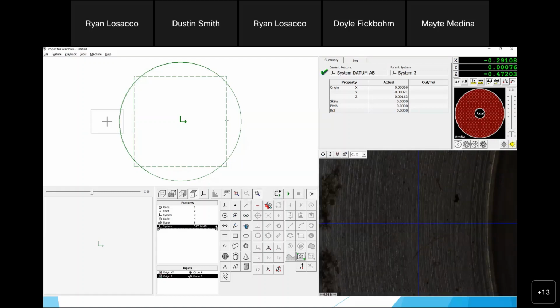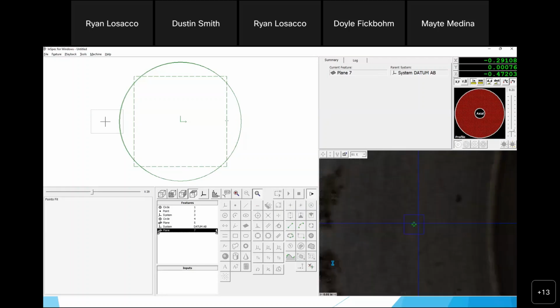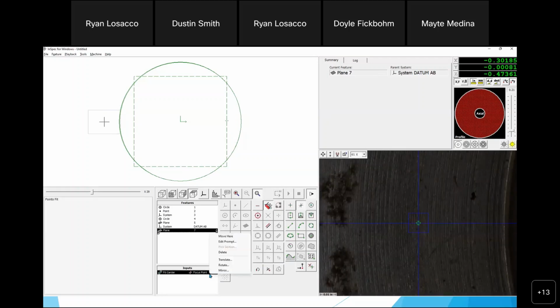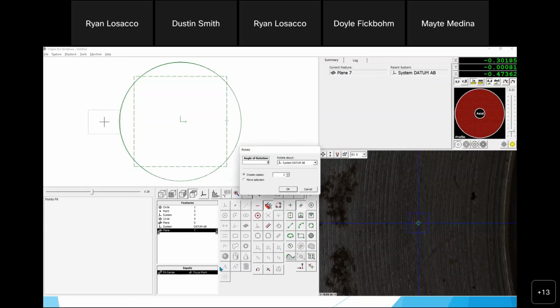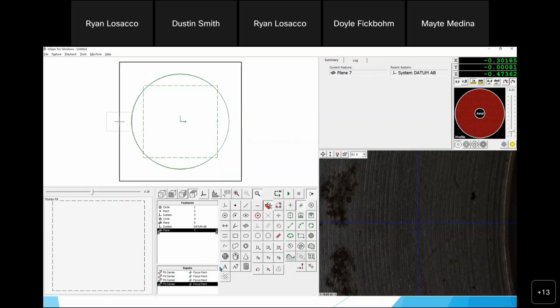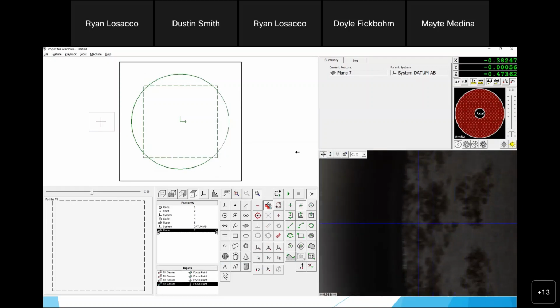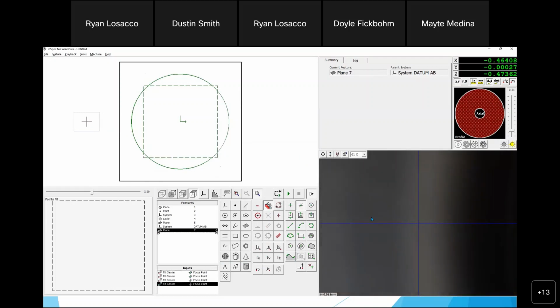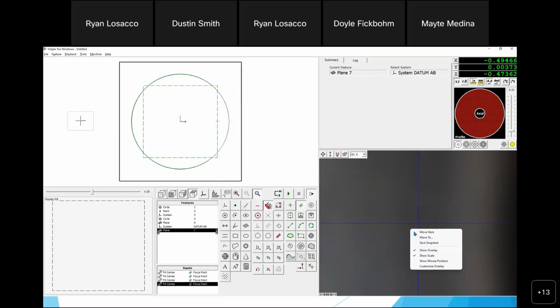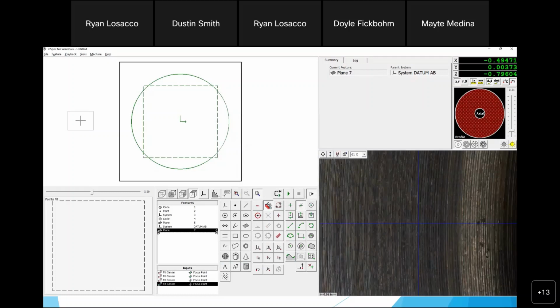surface. I'm going to do plane, focus point, right click, rotate, 93. So I got that plane. So I'll do that again. I come over here, my blueprint says the next surface down. I right click, move to, I just look at my blueprint. It says, okay, the next surface down is 796. Boom, I'm right there. I do another plane.